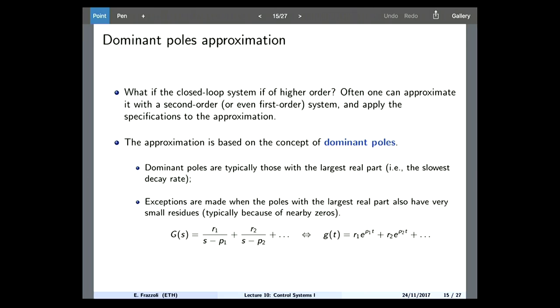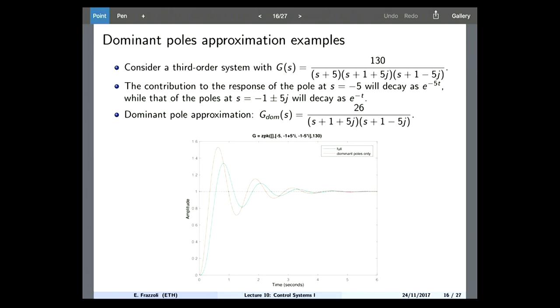So even though you may have an integrator in your loop transfer function, the closed loop typically will not contain an integrator, okay? So it will move, right? And what we are looking at for the closed loop specification is the closed loop poles, and in particular, the dominant closed loop poles, okay?